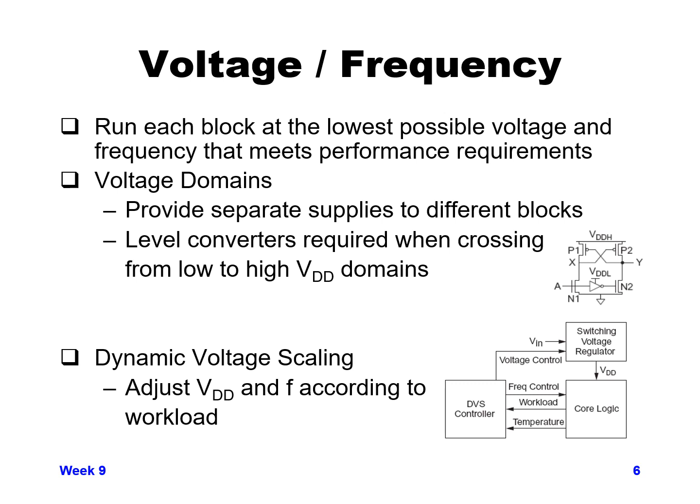And so that's one key way in a lot of modern IC designs, using multi-voltage domains and even multi-frequency domains, and just having each domain at the level of voltage and frequency that's needed for the performance that you need as an overall chip.